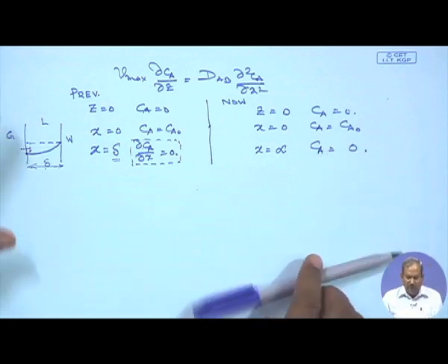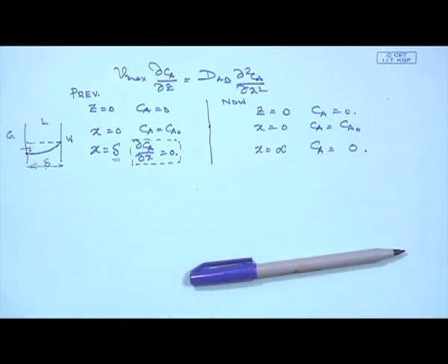and I would simply say that Ca is going to be equal to 0, which is true, because if this is the thickness of the film and A molecules are only very close to this point, because it cannot penetrate much, then whatever happens at a point far from the interface is, mathematically speaking, at an infinite distance as far as the A molecules are concerned. And what is the concentration of A in here? It is 0, nothing. No A exists at that point, since A exists only up to this point.